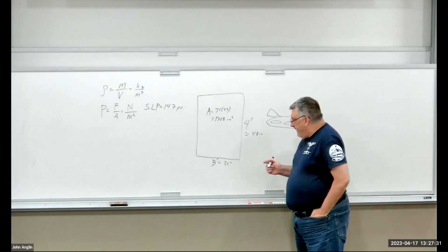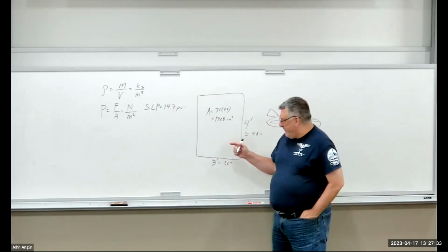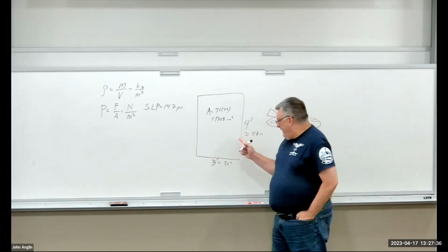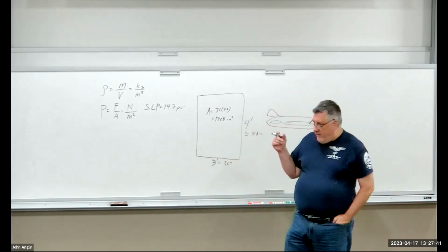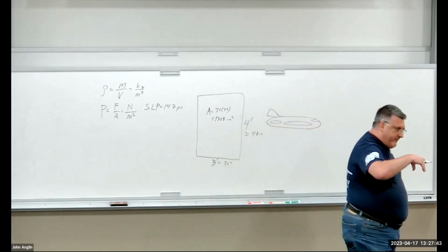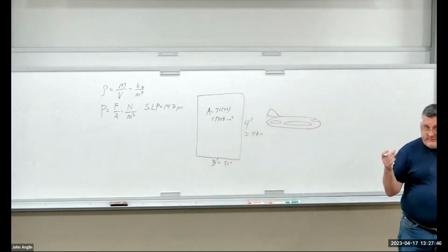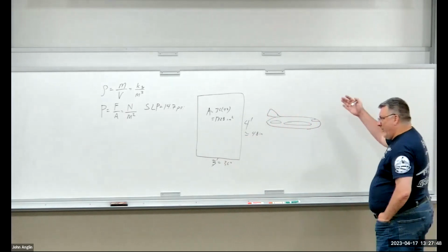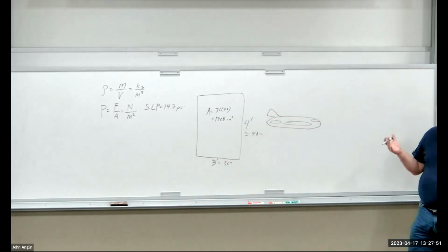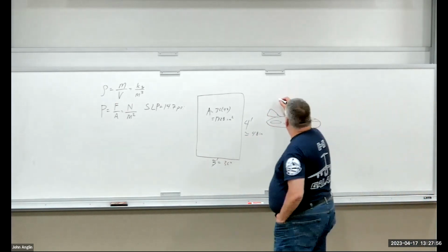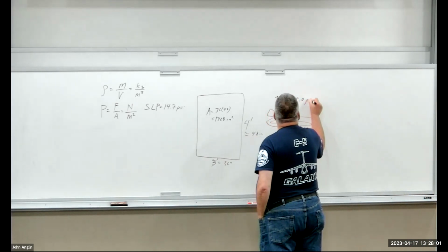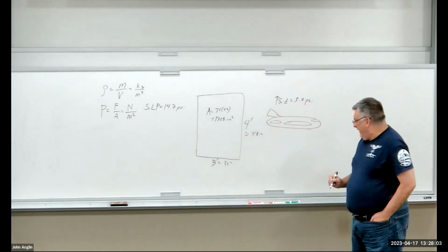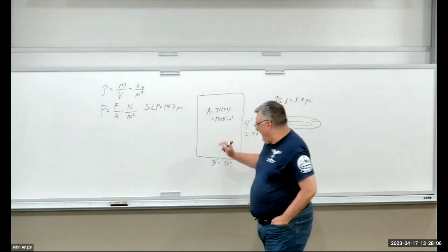Well, okay. How much pressure is against this door? We know that, let's just say, our differential pressure between the inside and the outside of the aircraft is 5 psi, just to make the math easy. So our PSID is 5 psi. That's a pressure, and we have an area.